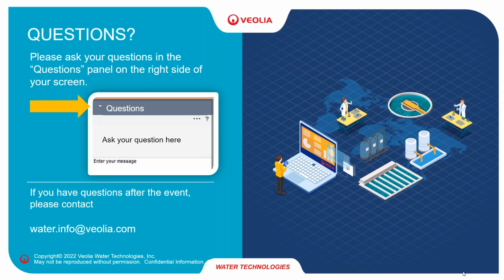So far, all studies were limited to the K5 media. The objective of that media is to provide biofilm surface. The K5 offers quite a lot of surface, with a specific protected area of 800 square meters per cubic meter. At the same time, we want a media that is somehow porous, with openings allowing water to flow through the media.